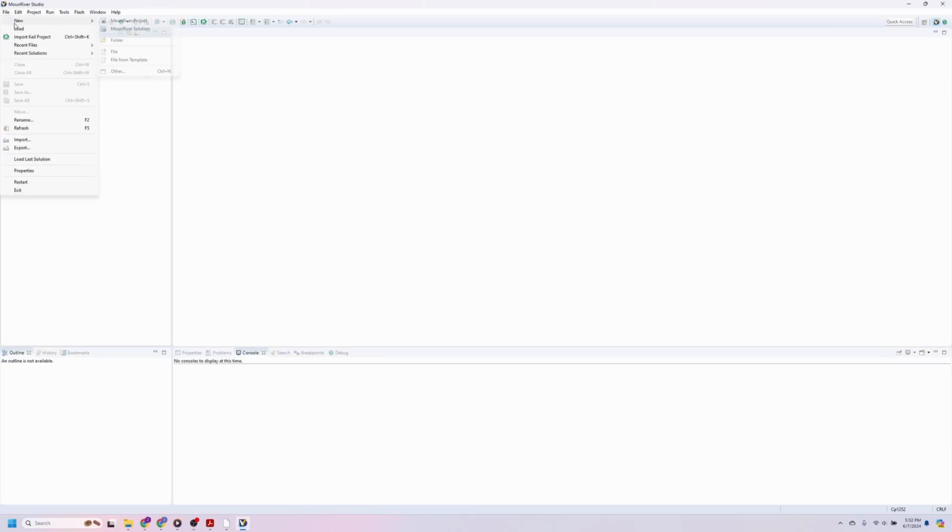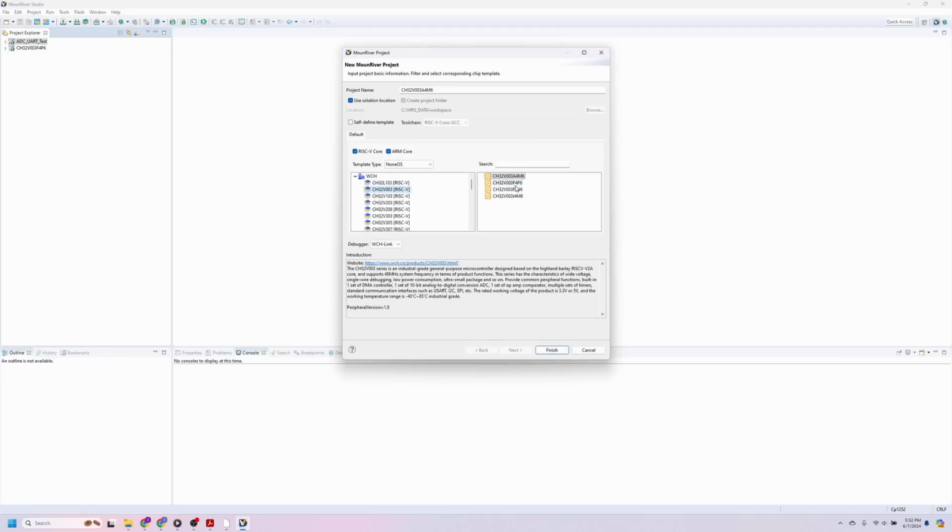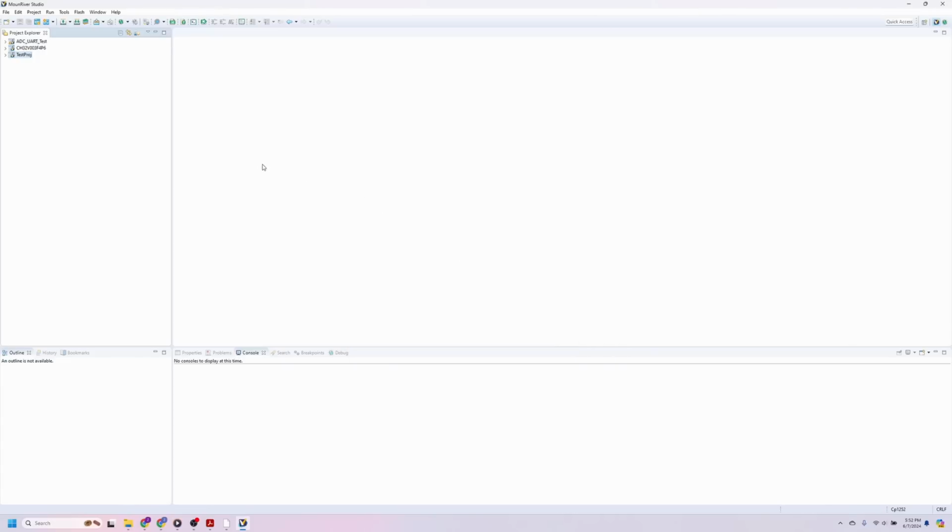When you open MounRiver and go to create a project, you basically just need to provide a name and select the chip you're using. Click OK, and that's it. All the start code and the HAL drivers are there and ready to use. The start code sends the system clock rate and the chip ID over UART, as well as has some UART echo functionality. Without making any changes to the start code, I compiled and flashed it just to verify that this at least worked.